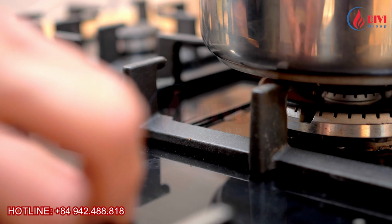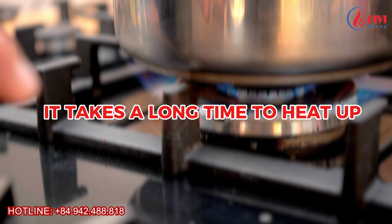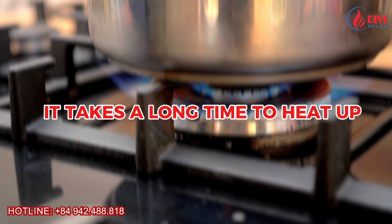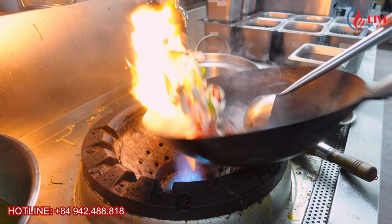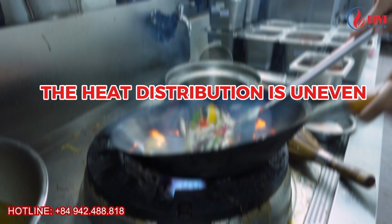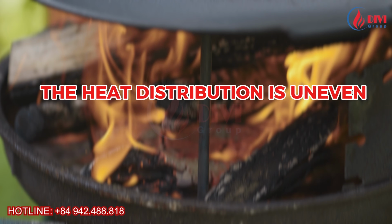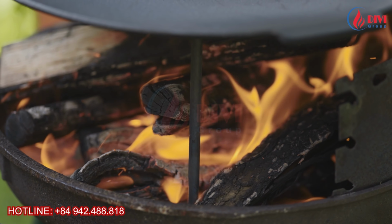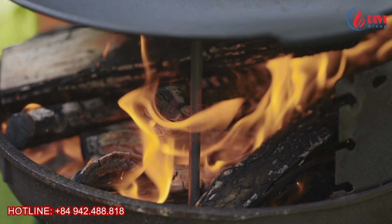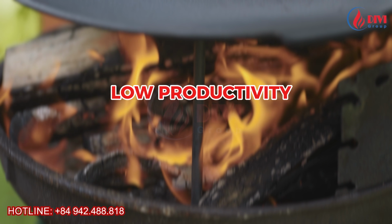This method has several disadvantages. First, it takes a long time to heat up. Boiling water or a processed solution can take 30 minutes, 60 minutes, or longer, depending on the tank size and heat input. Second, the heat distribution is uneven. The bottom of the vessel becomes much hotter than the rest. Without proper control, the product may burn, scorch, form deposits, or suffer from quality issues. Third, low productivity and heavy reliance on manual labor.